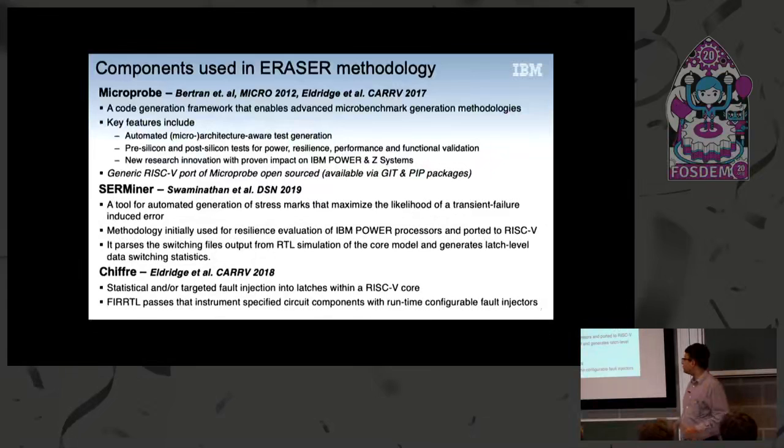And the HCR miner tool looks, as I mentioned, at these switching files and generates latch level switching statistics. And finally, there's a fault injection tool that was developed by Skylar, and it looks at statistical and targeted fault injection into latches within a RISC-V core. And this leverages some of the FIRRTL passes that he had talked about, and it's got a wide range of applicability even in this space.